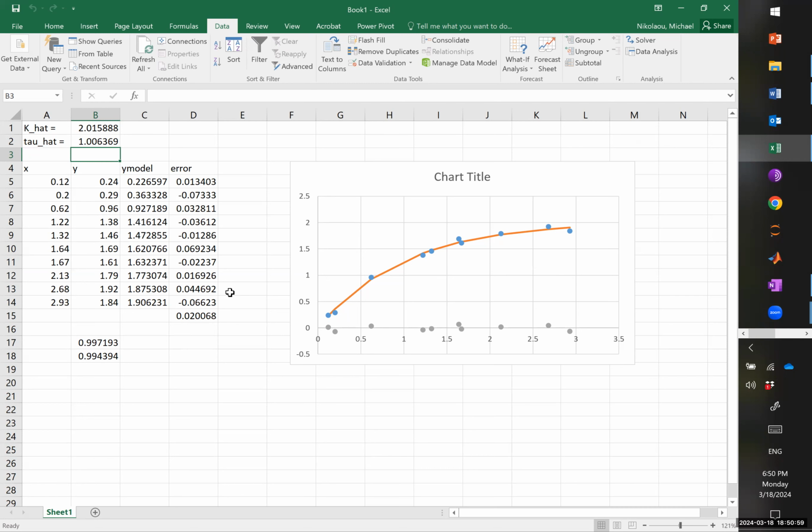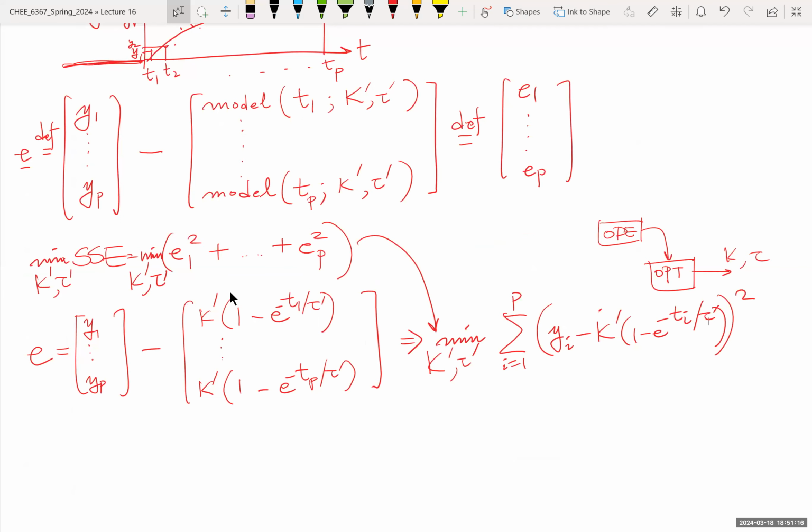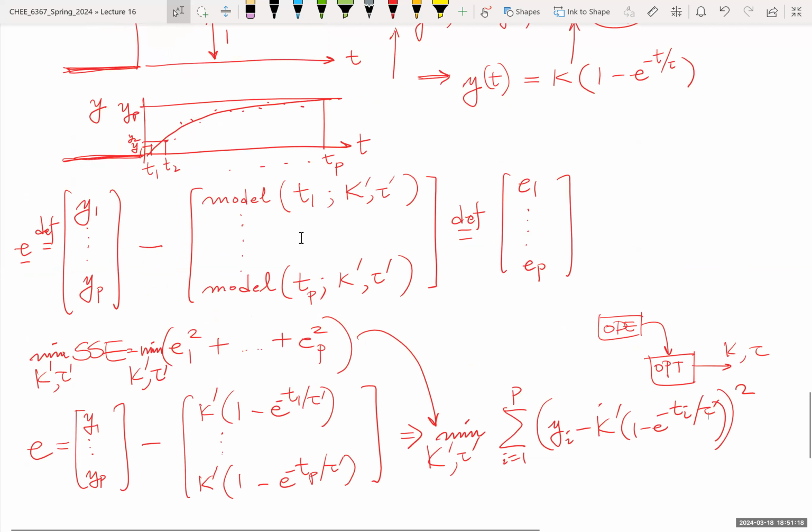So this stuff can be used now, like I said, more and more these days, this nonlinear regression idea. And the one key element here was that the model structure mattered. In what way did the model structure matter here? It mattered because A, we knew what to expect in the parameter signs. The gain is positive, the time constant is positive. So we'll use positive initial guesses.